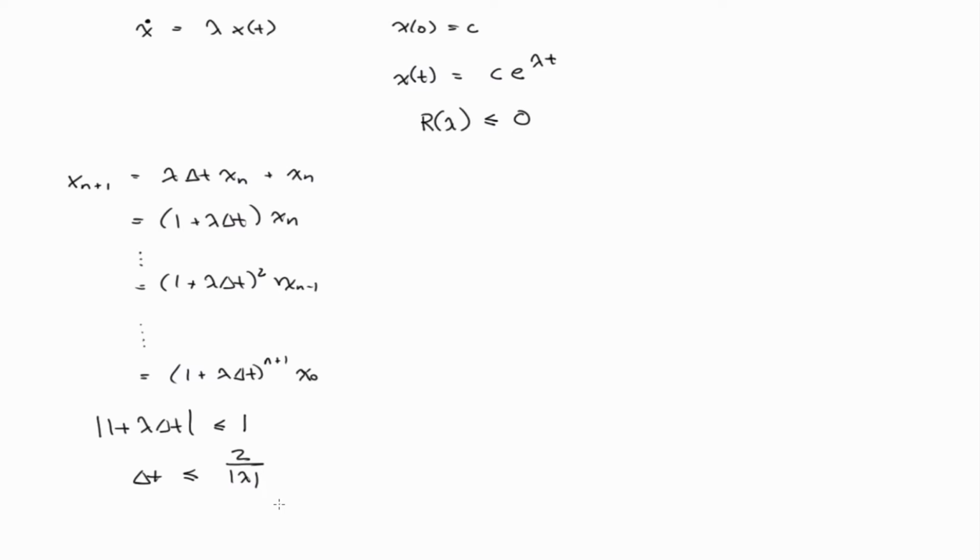because if you think about a mechanics problem, these lambdas turn out to be eigenvalues of the problem. They're like the fundamental frequencies, right? And so essentially what this implies is that the time step must be small enough such that it can capture the frequency or be able to capture the propagation of a wave across an element.